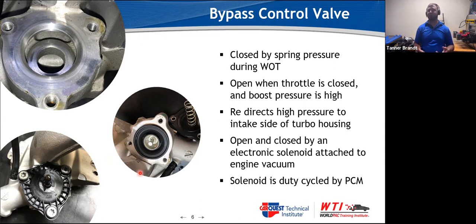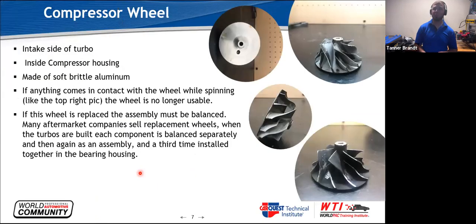It's easy to take off. It's 3 screws on this one. Most of them, it comes right off. I can't speak for every turbo out there. Most of them you can buy just the parts. Also, most of them are like a neoprene, so the oil really doesn't seem to hurt them. So most of the time you can wash them. You can normally order those parts separately. Even if, let's say, GM didn't have it, if you were to find the manufacturer of the turbo, you could call a rebuild facility like where I had worked, and be able to find the part numbers for that, say from Garrett or BorgWarner or something like that. So that's an option, and note that if you have turbo surge, that's something that you need to look at.